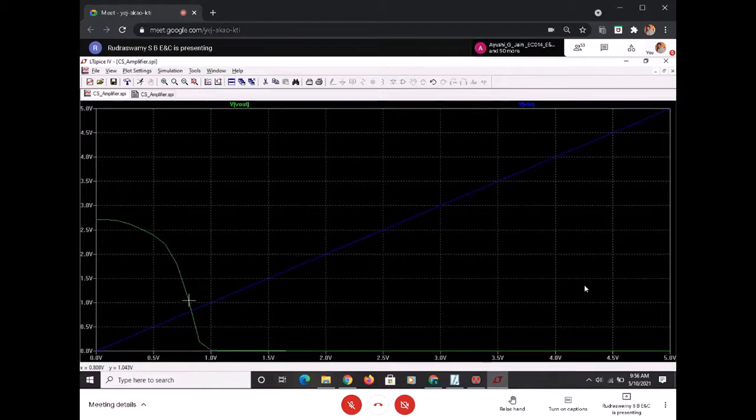Typically for the inverter you had seen the transient analysis. Similarly here also, but you can see that even though VDD is from 0 to 5, the output is not having a transition from 5, it happens somewhere at 2.5 something. So this is an amplifier now. We'll see what exactly the output will be now. This is the operating point. You bring the bars here and you can check, or I can directly go and intersect here, and correspondingly you can see the y direction values varying as the cursor moves.